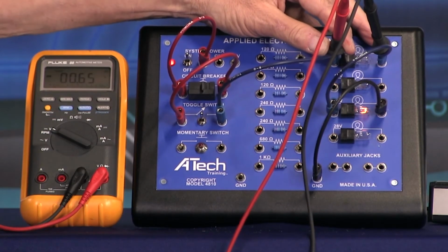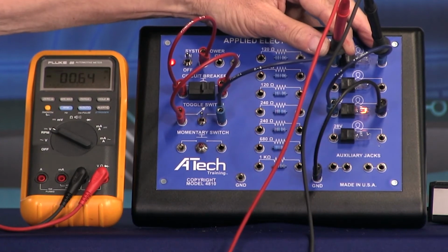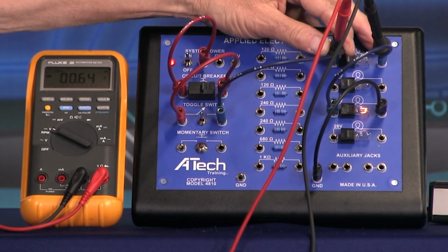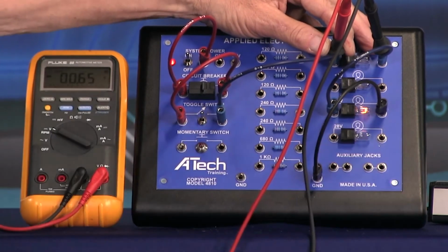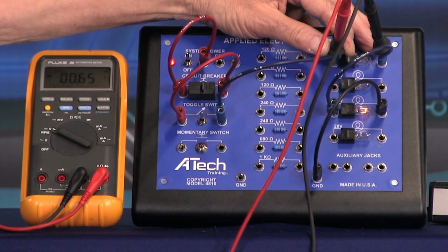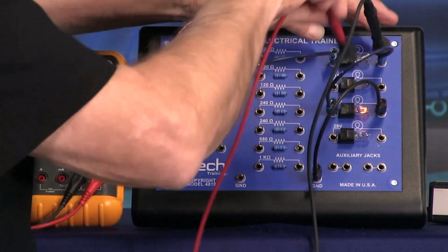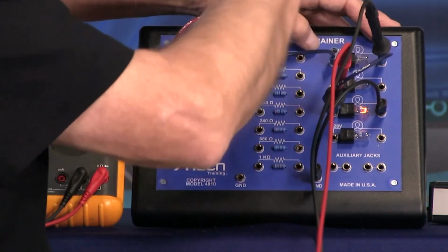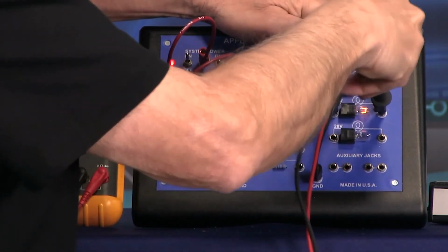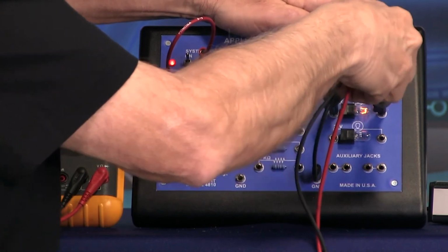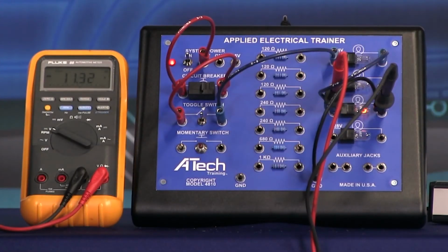Well, if that was only one load, I should have used all the voltage. Did I? The answer is no. So I know there is an additional load in the circuit. That could be voltage on the ground being used. So I'm going to go over here. Red's going to go in to that one. And I used 11.32.